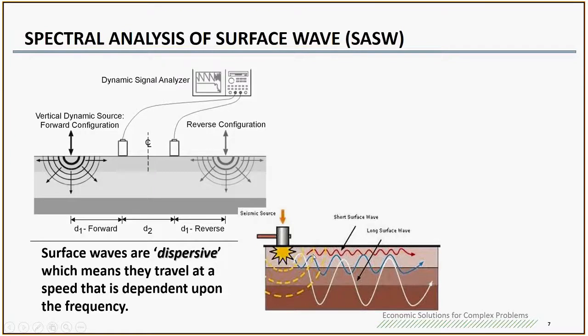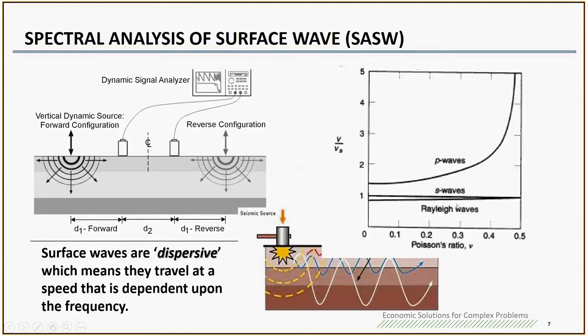For example, based on the data, you just measure this surface wave back at the receiver, so you can calculate the Rayleigh wave velocity for this layer. If you go deeper, the wavelengths become longer, so you measure a different wave. Once you have the Rayleigh wave velocity, you can use some correlation to calculate the shear wave velocity, Vs.